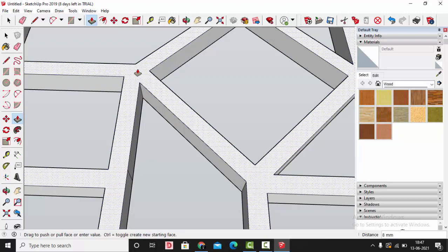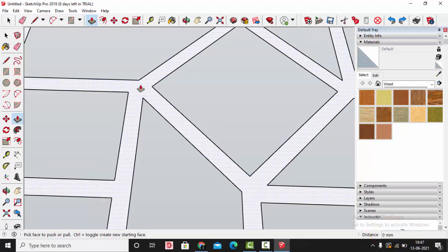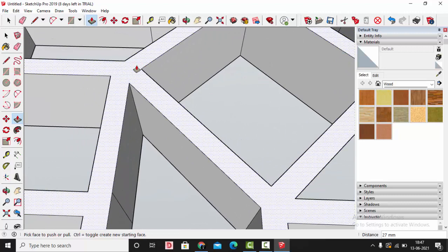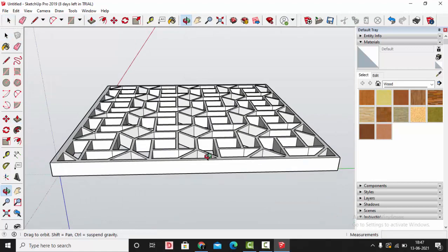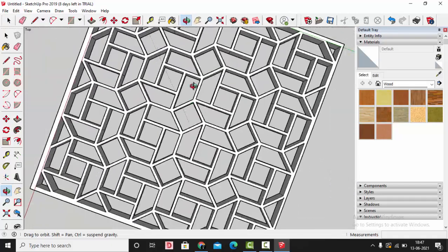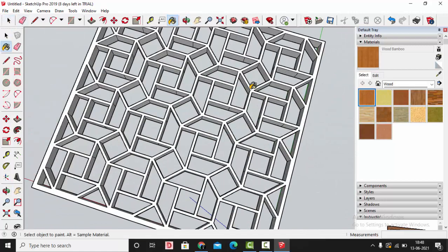And here at the bottom, if you observe, it shows the number. Okay, so I'll go back again. You need to select where this dotted surface is selected. Use the left mouse button and drag it up. Now you want to have it 25, so just type 25, enter, and it gets to 25. Zoom in. Now if you check, the other side surface is also turned a white surface, not the blue. Okay, now you can select.